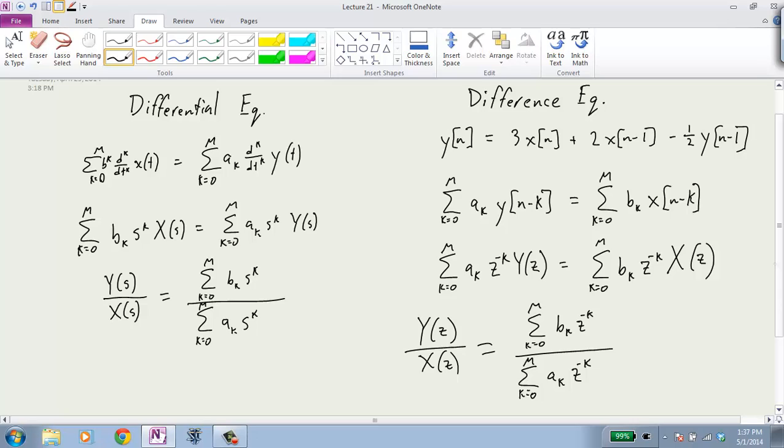But anyway. Okay, so then immediately we see that we can get poles and zeros, and we can know whether a system is stable. We can interpret the Fourier transform, if it is stable, by looking at the appropriate location within the Laplace transform. So for example, in continuous time, we would get the Fourier transform by looking at the imaginary axis. In discrete time, we would get the Fourier transform by looking at the unit circle.